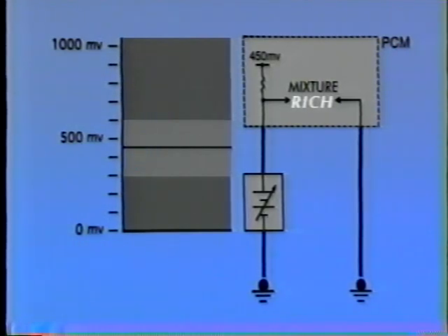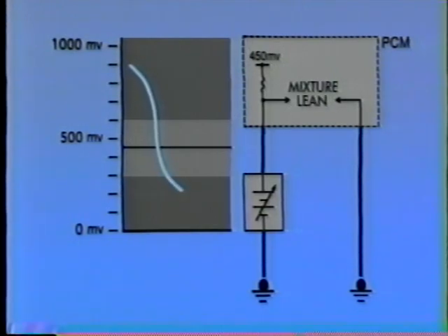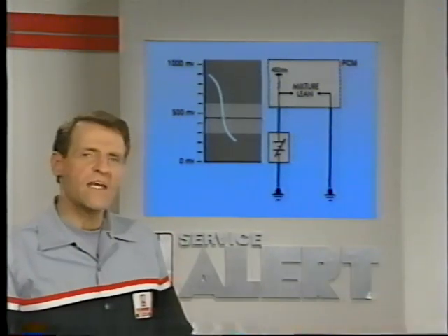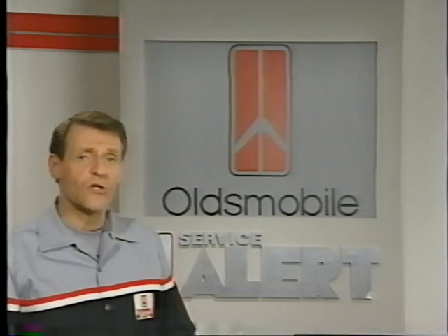With a lean air-fuel mixture, there is more oxygen in the exhaust. As exhaust oxygen content increases, oxygen sensor voltage decreases. As sensor voltage goes low, it pulls voltage at the controller's input below the reference band. The controller reads a mixture-lean signal. The controller takes 80 oxygen sensor readings per second. Over time, it not only interprets each individual signal value, but also looks for trends.